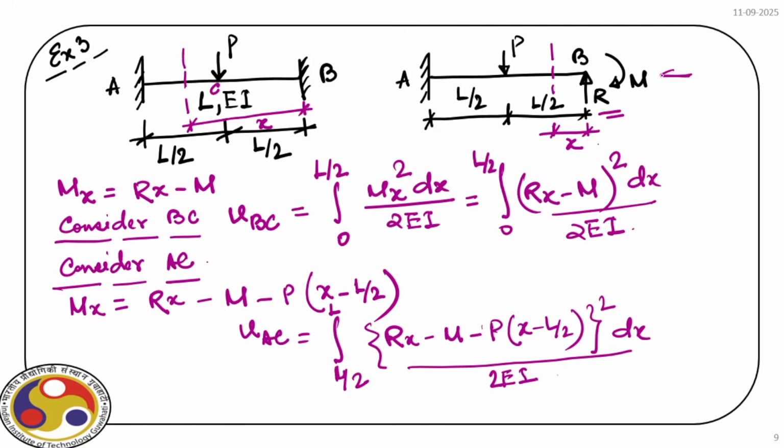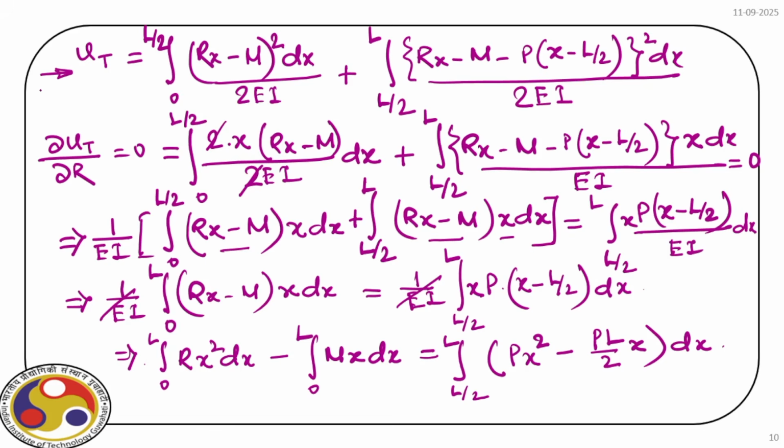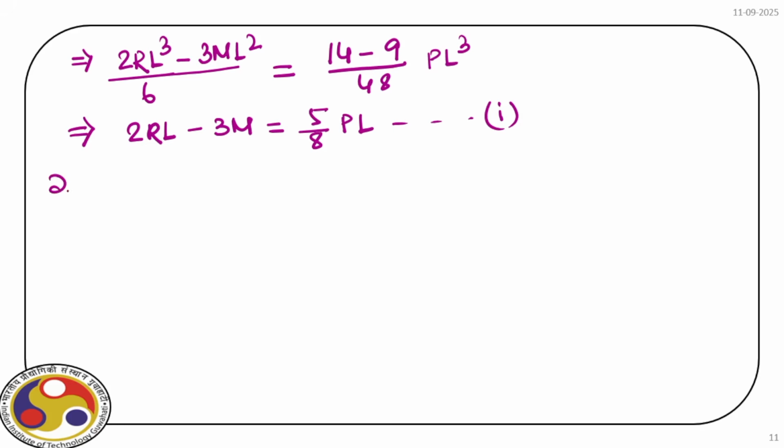As you can see, the moment we remove this support, and because of the presence of this fixed support at the end B, the rotation at the end B is 0, and therefore if we differentiate UT here with respect to M and put that equal to 0, we satisfy the boundary condition. Okay, so let us do that.